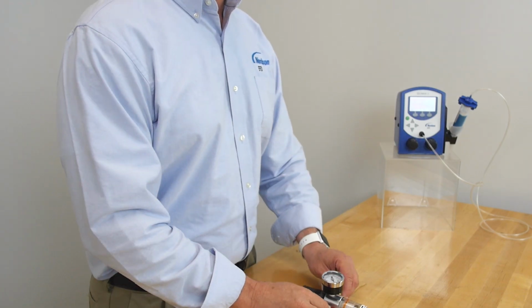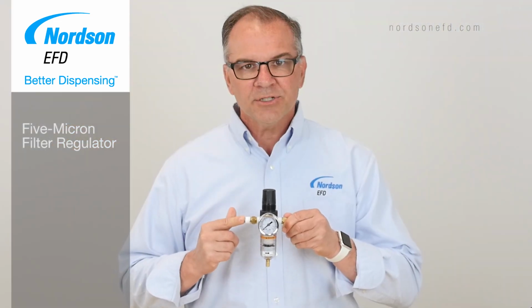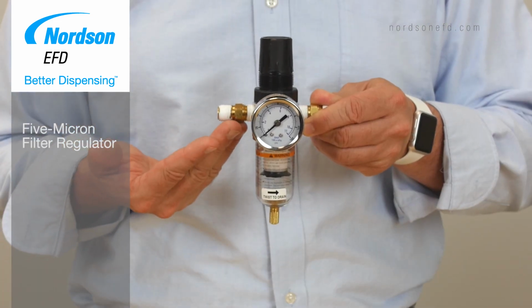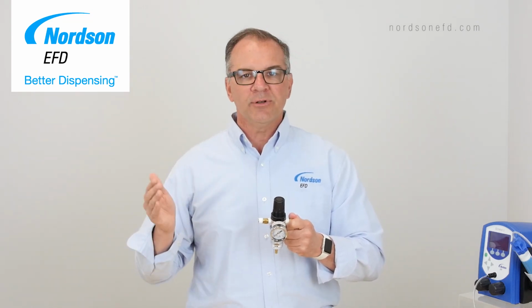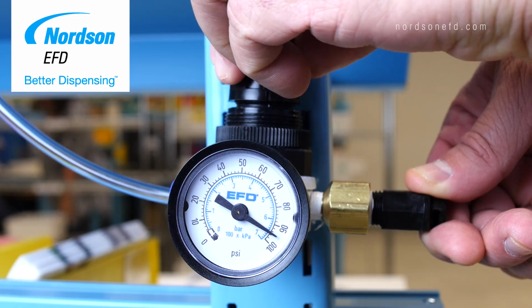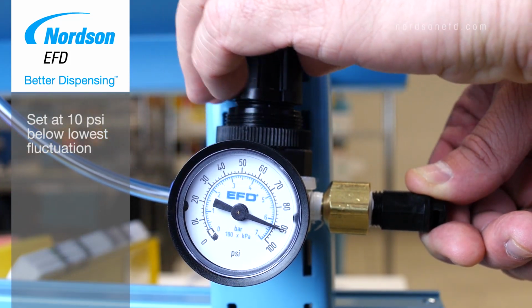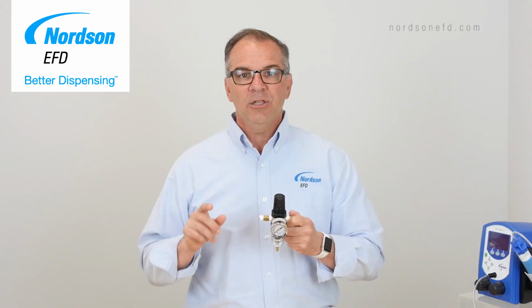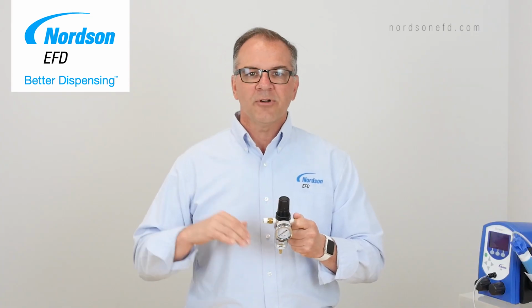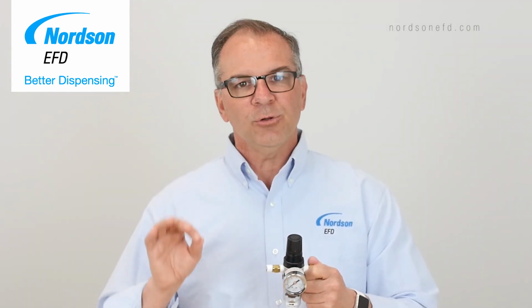So that's why it's important to use a 5-micron filter regulator in between your plant air supply and your dispenser. So let's say your plant air supply fluctuates anywhere between 90 to 110 psi. We recommend setting the filter regulator at 80 psi. That's 10 psi below the lowest point of fluctuation. By doing this, you actually buffer the dispenser from the air fluctuation. This will allow for precise and controlled dispensing.